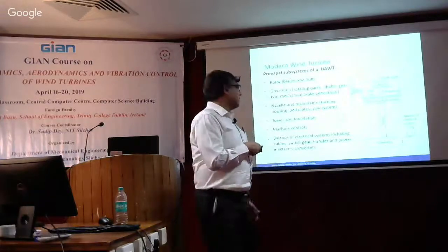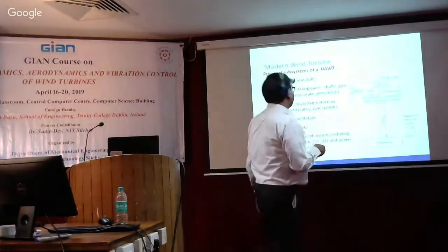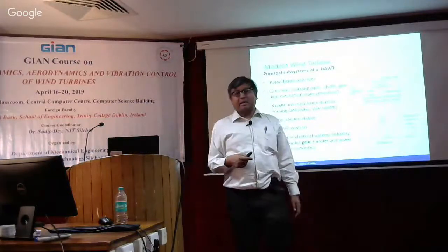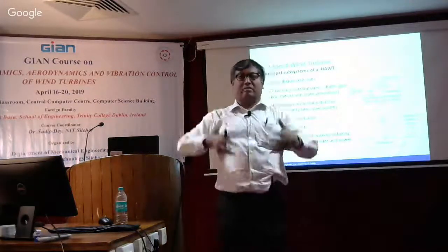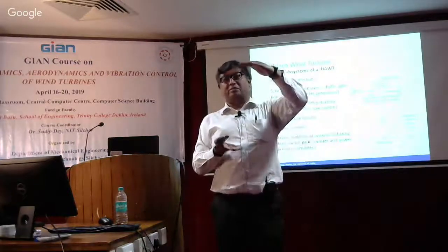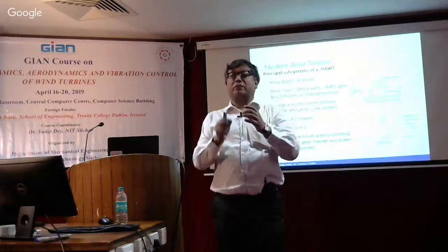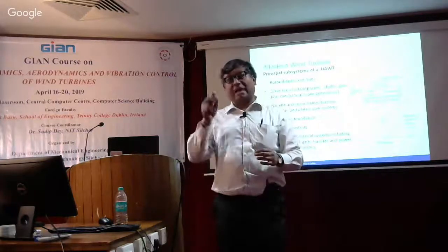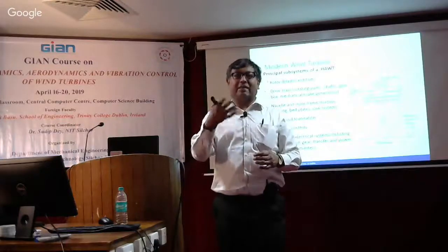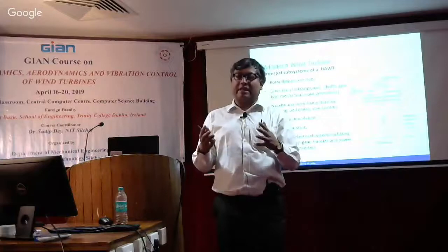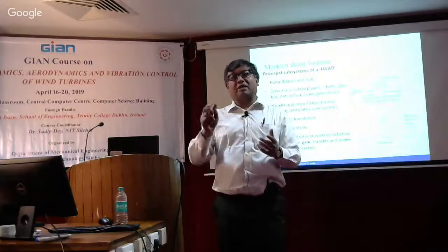And normally the failure happens at connections and stiffening systems in towers. The tower is not, again, an integral single design of the whole tower. It's made of splices. And so locally where the joint is, the connections fail. So the reliability of the connections is poor. As in the case of offshore structures, the structures are overall more reliable, but connections are not.